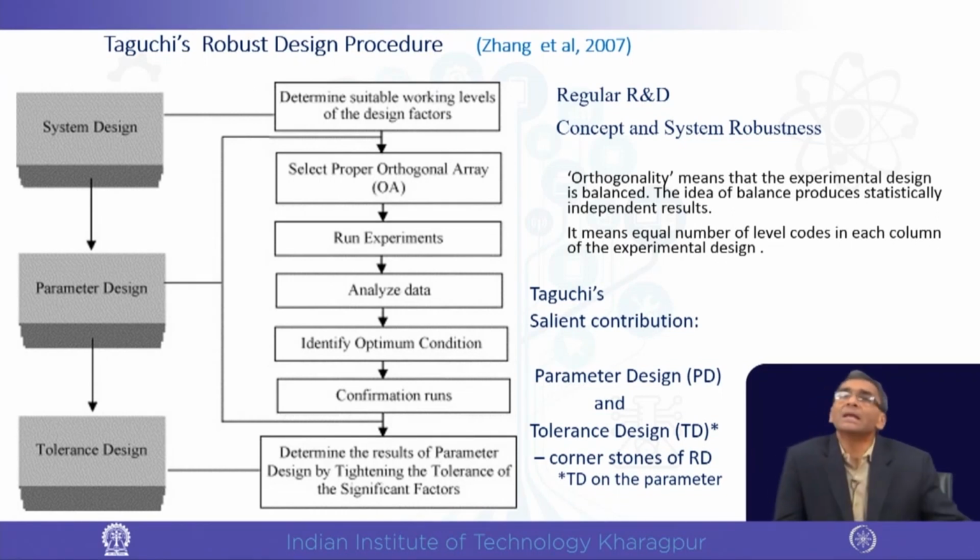What is tolerance design? In short, when we decide a parameter to be of a certain scale and set it, we are saying that this parameter should also not fluctuate too much. If the parameter is 60, to what extent does it give the best result, whether 60 plus or minus 1 or plus or minus 2, etc.? Within which range we have to come down so that the performance is intact. So how tight the tolerance has to be made is the direction given by the tolerance design.